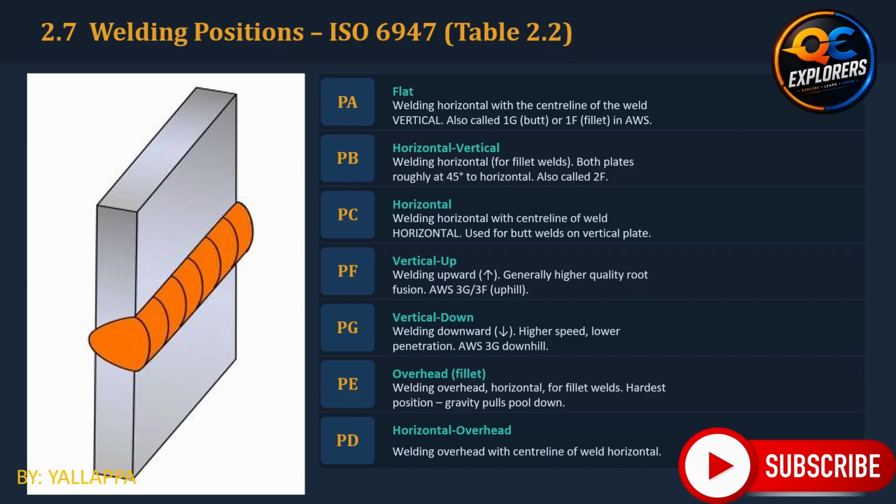PA represents the flat position. This is generally the most favorable position because gravity assists control of the weld pool. PB is the horizontal vertical position, commonly associated with fillet welding. PC represents the horizontal position for the relevant butt weld configuration.